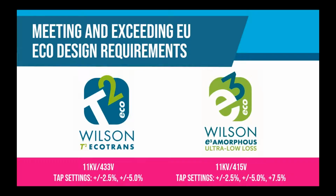Now, just to show you some changes on the standard voltage ratios that we have. The Wilson T2, the one that meets Tier 2, will have a voltage ratio of 11 kV to 433 volts, with tap settings of minus and plus 2.5% and minus and plus 5%.